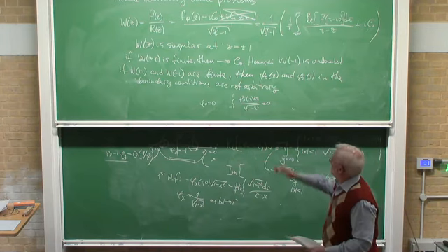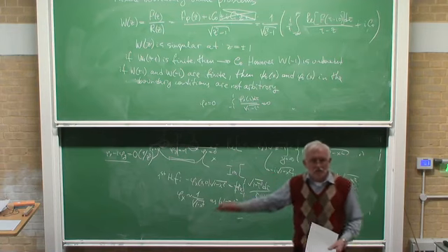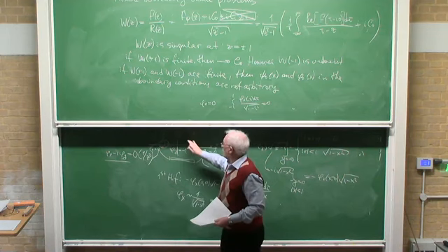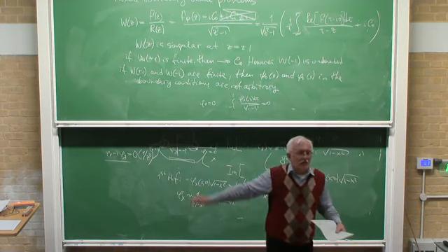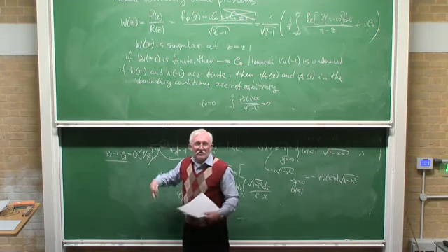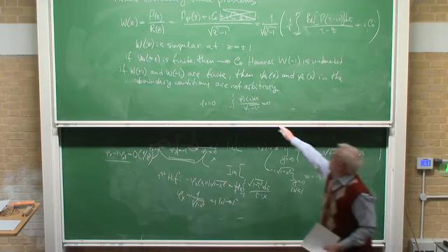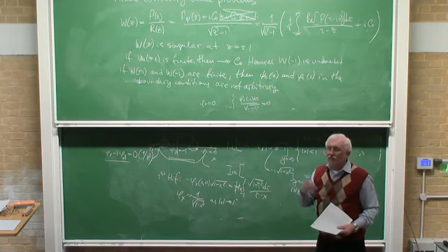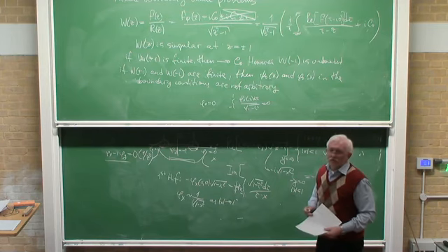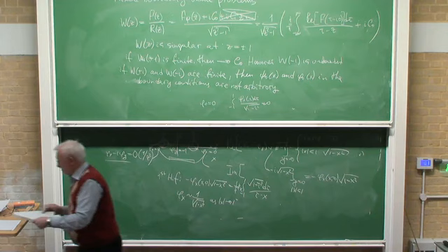And again, if we formulate the problem of impact for the velocity potential, then velocities are allowed to be infinite in that sense. But if you formulate it for, say, the displacement potential, meaning the integral in time, then the displacement should be finite, right? And then this condition gives the equations for the size of the wetted region. So they actually define how the solution behaves. Any questions? We still have 4 minutes.